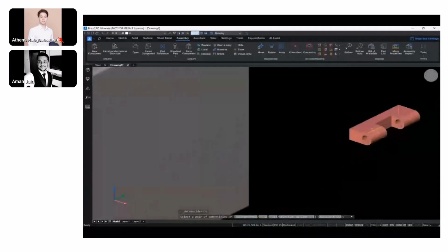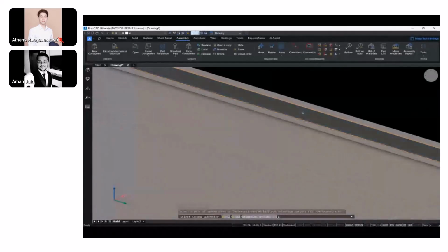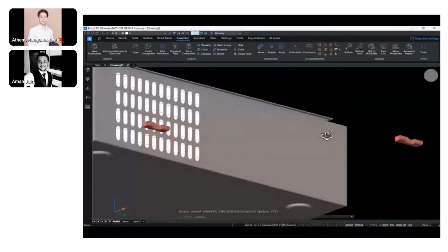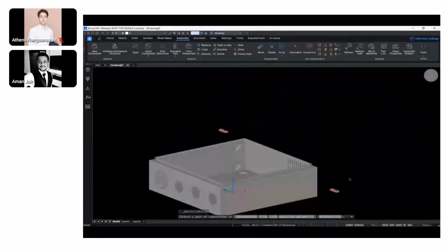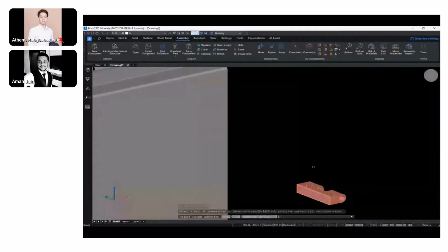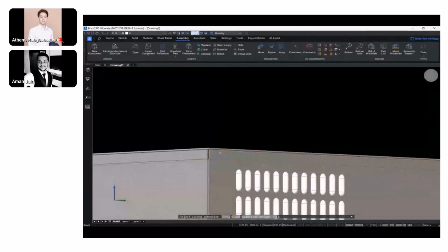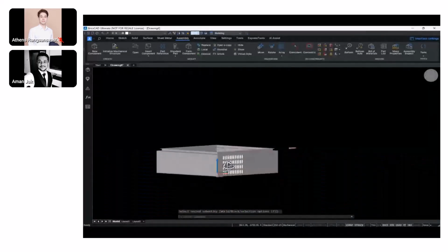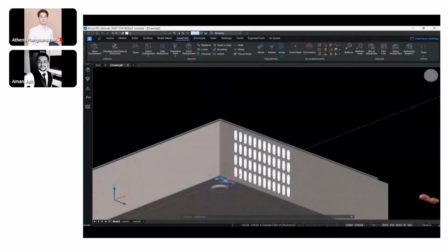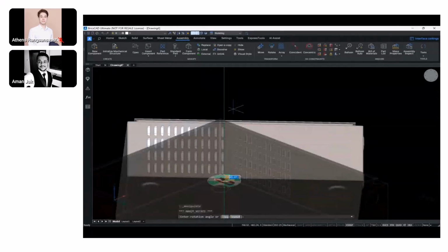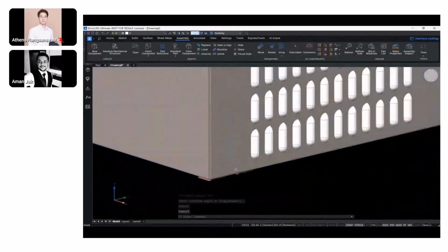Again, very plain and simple, just applying coincident constraints so that it stays in place. And once I've applied the coincident constraint, all I need to do is give them the distance constraint from the faces. I'll apply the same thing over here as well. First, a coincident constraint to this face. And as you can see, I'm reiterating this because this is the interoperability feature of BricsCAD. Sorry for that, just selected the wrong component. Let me select it once again.